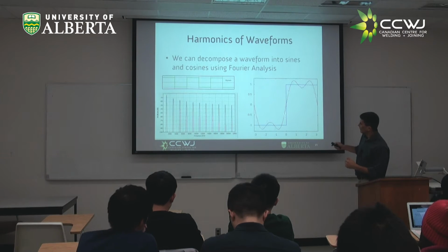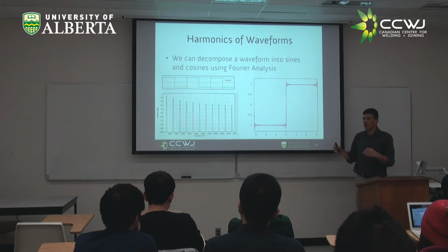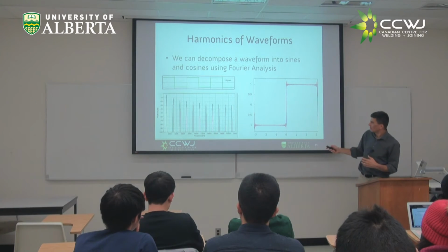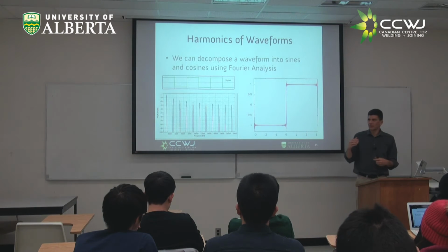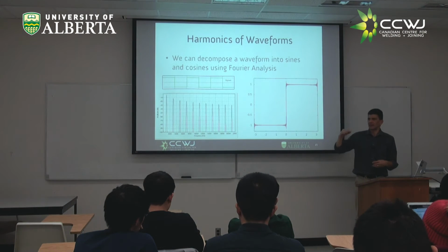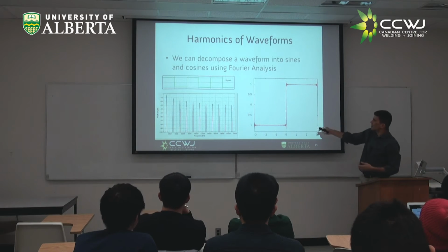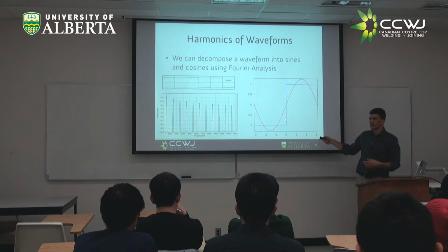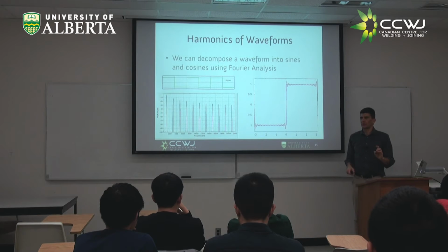Look, this is one sine. Now 2, 3, 4, 5, it gets bigger and bigger. And that's how you form this square waveform. But you need to have very high frequencies to have this kind of sharpness. And at those very high frequencies, the leads kill it, right? And in the end, I might have wanted to have a sharp square waveform. What would be a good use of a sharp square waveform? What would be a reason to have one?